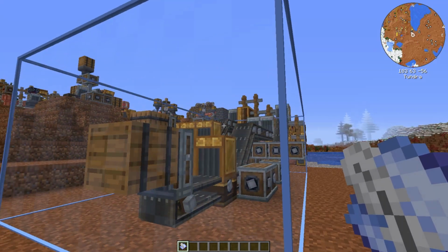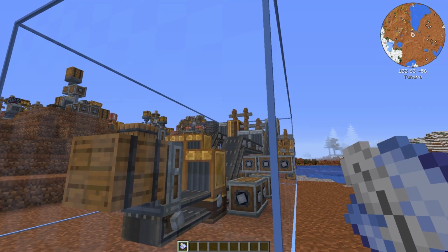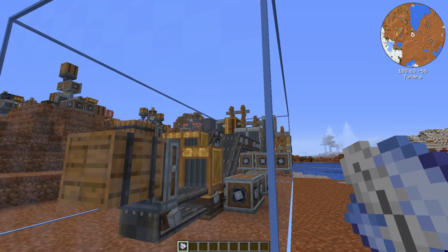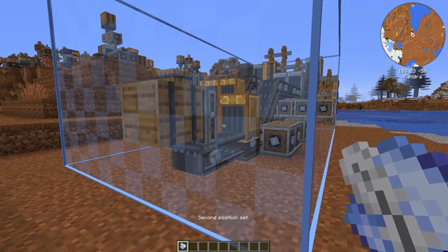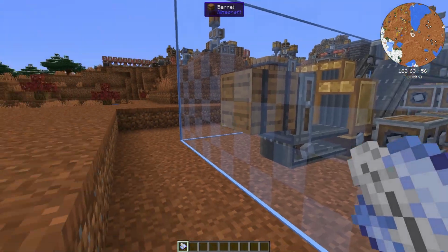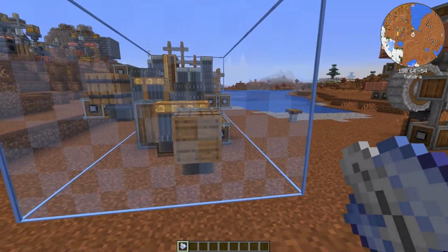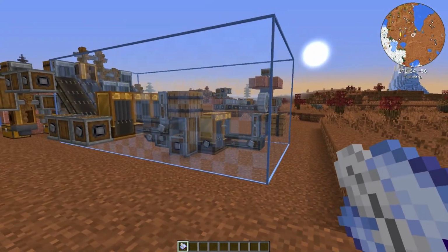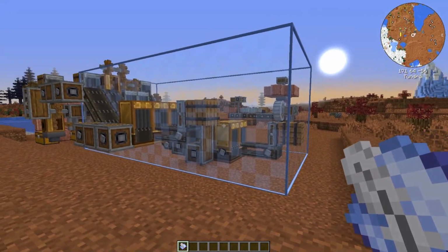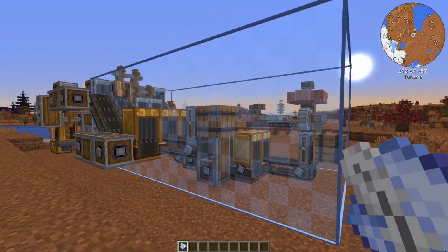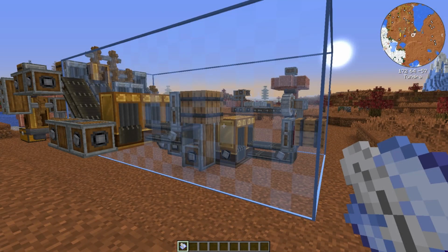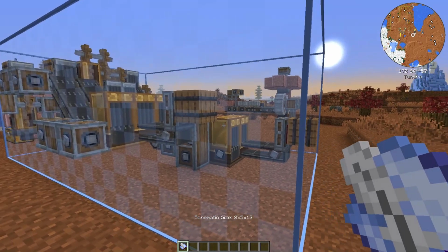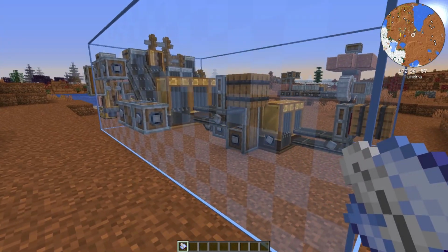This can get a little confusing, but we can always tweak this a little bit later. So let's go ahead and push that right there. It sets the second position when you click down on it again with the right click. And we can go over here and we can see that we are shy of this side here. So facing this with our cursor against this side, if we scroll the mouse wheel back by holding down Control, we can move the whole box out this direction.